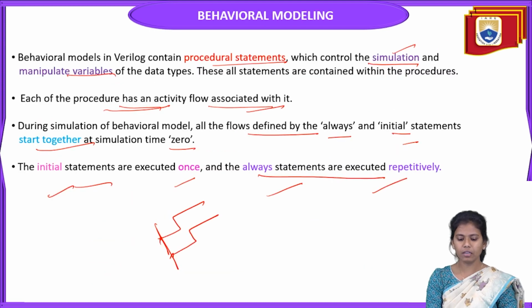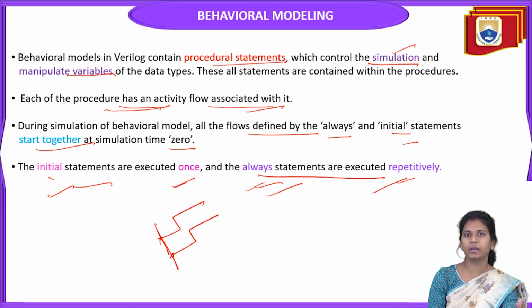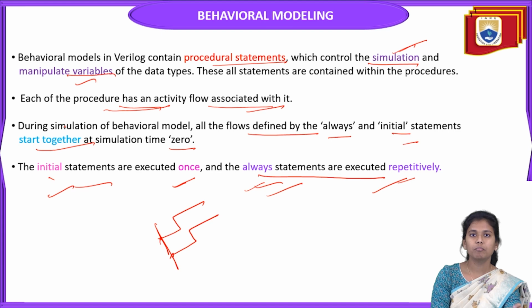Always remember that initial statements are executed once, whereas always statements are executed repeatedly, as in the example we have discussed. Initial statements execute only once, whereas we can repeatedly execute as many always statements as needed. This is also a very good model for developing a circuit which controls the simulation, and for manipulating the variables.